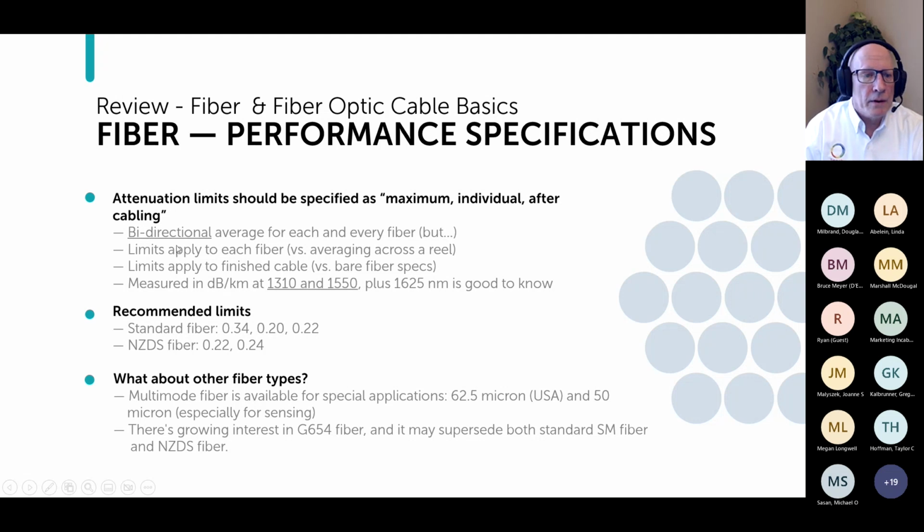The practical reasons are that dielectric cables, A, tend to have higher fiber counts, and B, they are produced in much higher volumes. So a typical OPGW strander is going to run around 5 meters a minute, maybe more, maybe a little less. Depends on the strander type. But usually you're dropping a reel a day on a stranding line, roughly per stranding line.